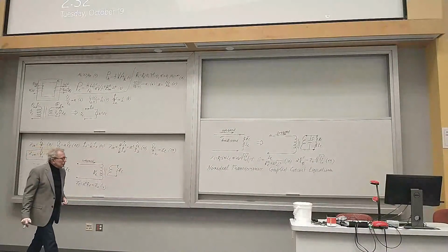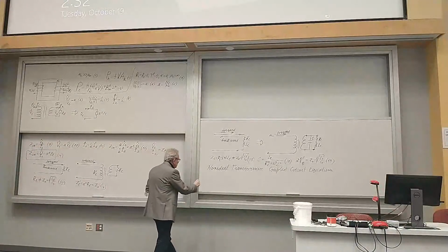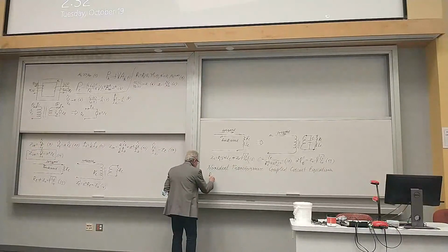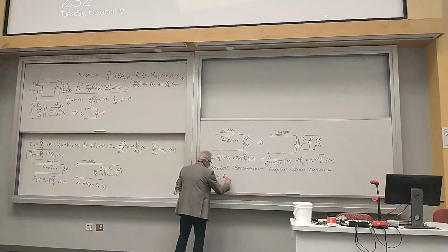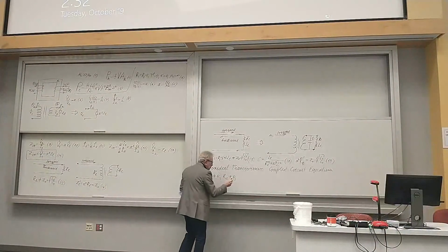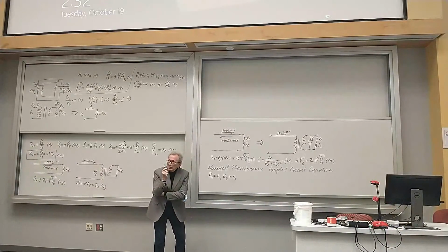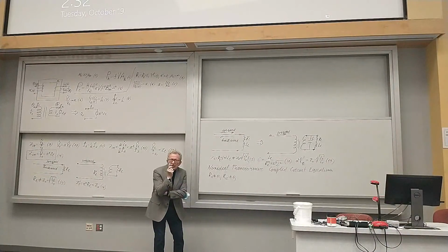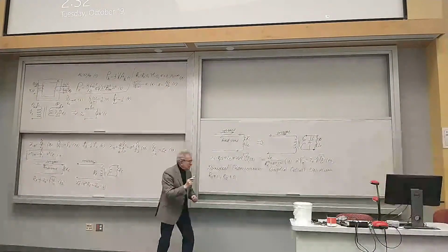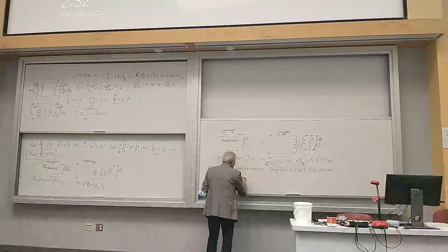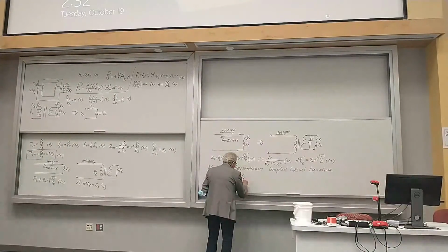For the non-ideal transformer, we will not neglect resistance, so we assume that the secondary resistance is not equal to 0. More importantly, and this is very important, only people in power engineering know this: we will not neglect the magnetic leakage. We will not neglect the flux linkages due to the leakage.